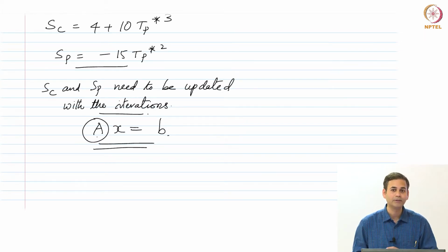In a sense you have to iterate the solution for certain reasons. One of them is of course if you choose an iterative method instead of a direct method. The other one is if you have non-linearity, because non-linearity you cannot solve directly. So, either you have to introduce a kind of outer loop where you update the coefficients of A. We will come to that discussion a little later. As far as this discussion is concerned, right now we are looking at, let us say, an iterative method, fine. Other questions?